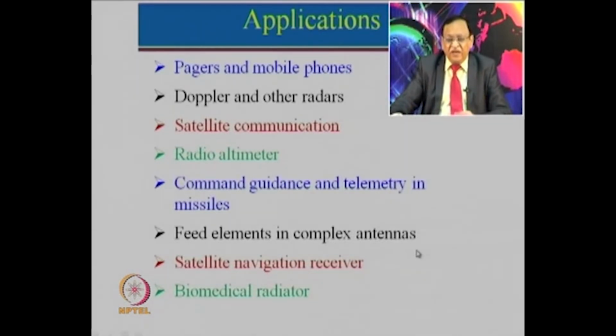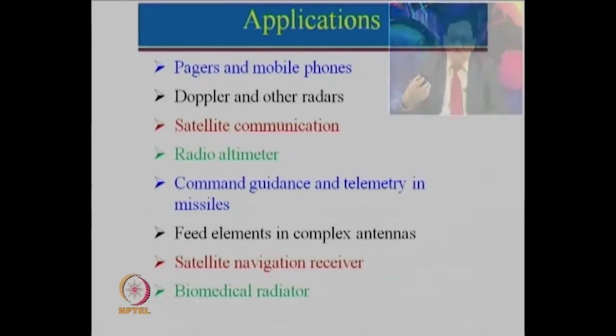In fact, more than a decade back, what we had done was we replaced the horn antenna of a 4 gigahertz parabolic dish. Remember, a decade back there used to be a large 8-foot parabolic dish which had a horn antenna as a feed. We studied the characteristics of the horn antenna which was feeding that reflector antenna, and we replaced that horn antenna with a microstrip antenna, and we reduced the size significantly. As we progress in this lecture on microstrip antenna, we will show you the details of that.